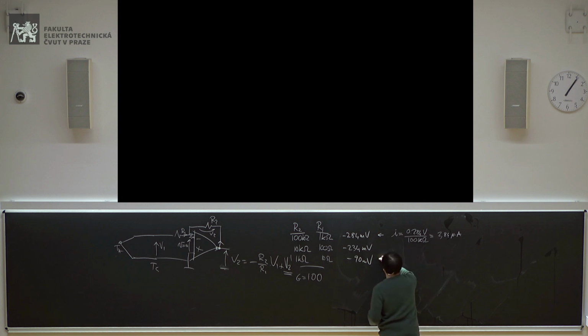Yes. And in this case, I get a current which is 0.09 volts, because you have 90 millivolts, divided by 1 kilo ohm. Okay? So it's about 90 microamperes. Again, is it true that if you use a lower resistance in the feedback, you get a bigger current? Yes, definitely. Because here we have 90 microamperes versus, oh, sorry, here is point, not comma. It's dot, not comma. Definitely we have 90 microamperes versus 2.8, let's say 3 microamperes. So definitely the current is much larger.